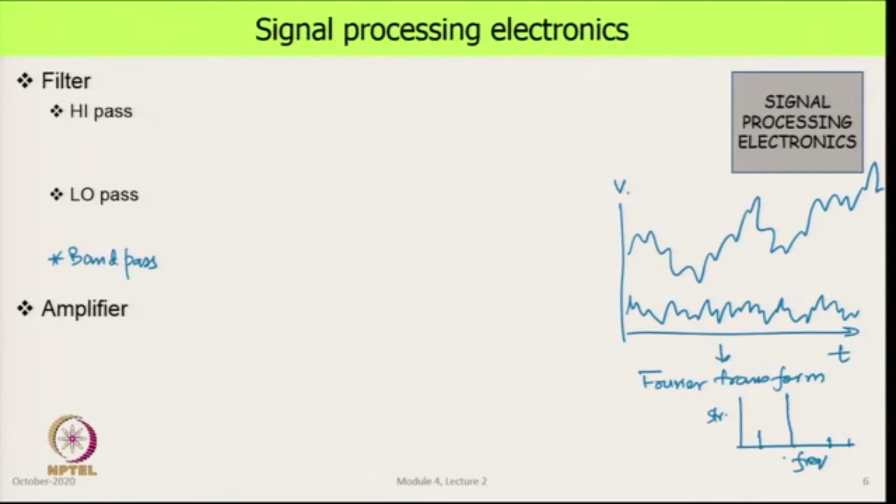A pure single line would mean that it is a pure sine signal, that is all. So, what it is telling us is that this signal is composed of an amplitude related to the frequency multiplied by sine, that is A_i sin(omega_i t + phi_i): the amplitude, the frequency, and its phase.